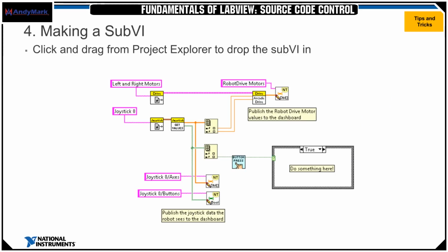The one after the icon editor. Sorry, guys. Yeah, so this is kind of the LabVIEW code I was talking about. You can see that it's a lot cleaner. It's a lot neater. My wonderful button press icon is there. You can color code all of your icons if you want, if they all have to do with one subsystem or one certain function. Color coding is a really easy way to note that those sub-VIs are related.